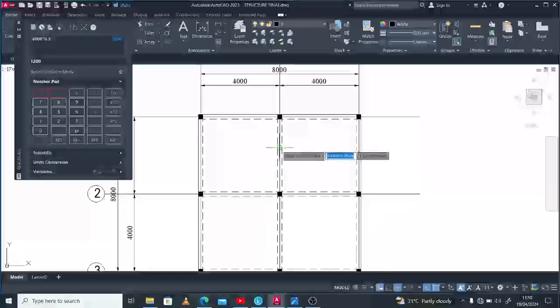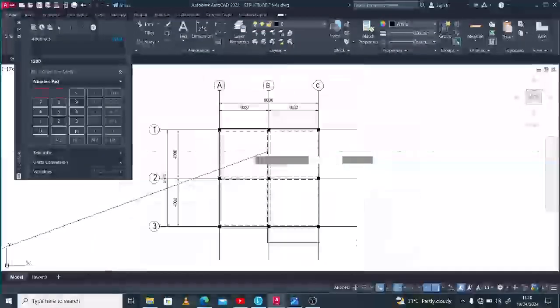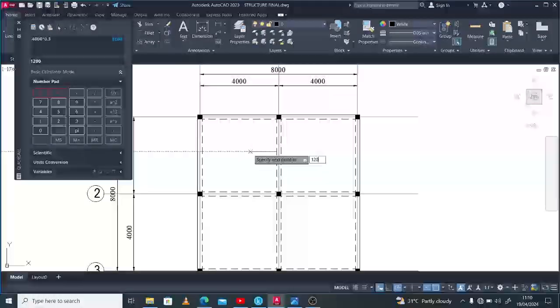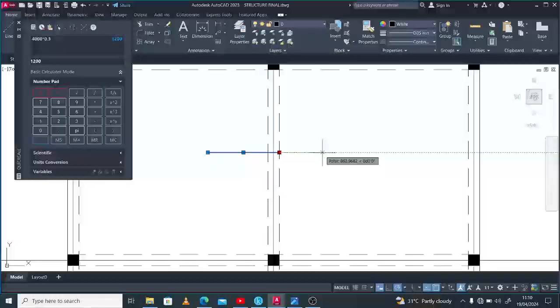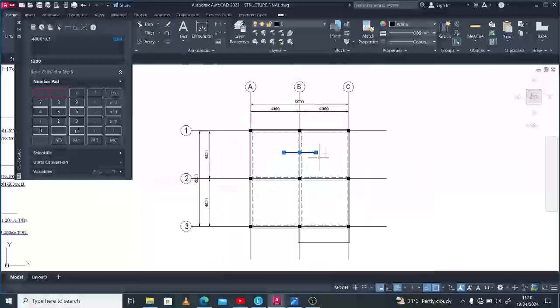All right, so what you're going to have from the face of your beam is going to be 1.2 meters. All right, so that's what we have. Then you move from there to the other span, 1.2 meters, as the code recommends. So you see, as it is, basically that's your top reinforcement for that beam.